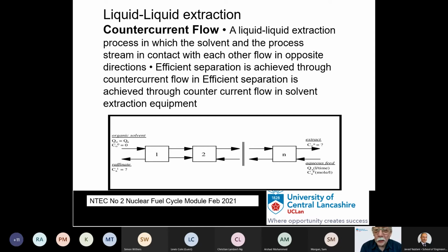When we use liquid-liquid extraction as opposed to ion exchange is something that you need to appreciate. Normally liquid-liquid extraction will be used on more concentrated solutions, i.e. let's assume any uranium in solution above 10 grams per litre, you would probably more likely consider liquid-liquid extraction. Anything down at 1 gram to 5 grams and less than 1 gram, probably ion exchange would be the preferred separation process.